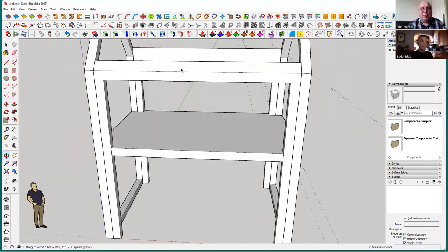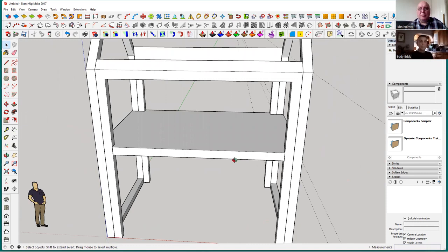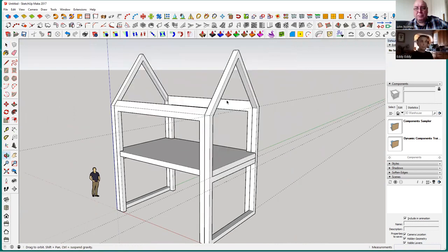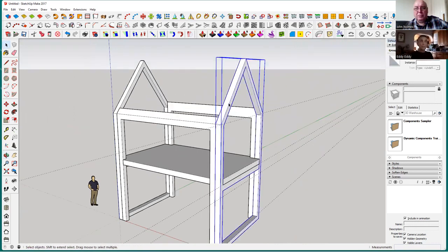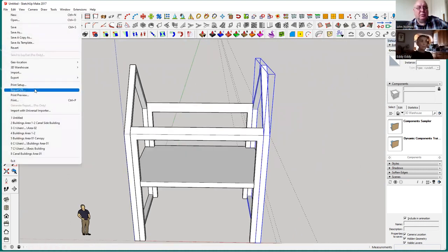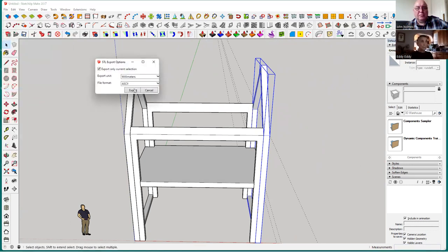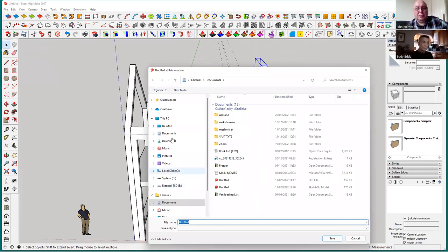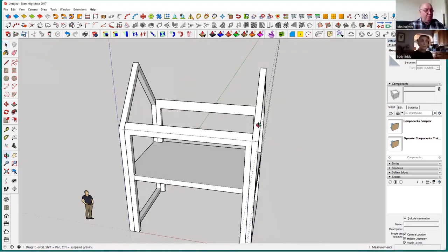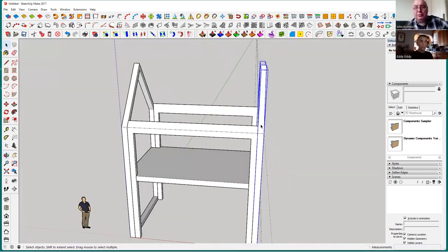And then it can be clad, roof, walls, and each one of these is a separate object now. So if you want to print them, this one here, go to File, Export STL, Export. We'll just save this in as all one, sidewall. And you do the same with all the other items. So it's one wall you need to do, one front, one floor.